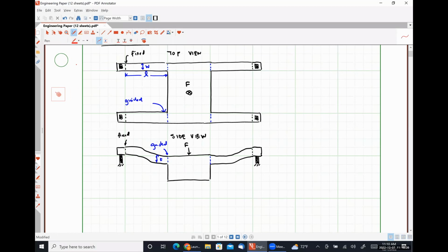So I'm going to put something here. Effectively, we have one beam that's experiencing cantilever deflection down, this guy right here, and then this cantilever is experiencing deflection up, and we're going to treat it as two cantilevers in series with some total amount of displacement.